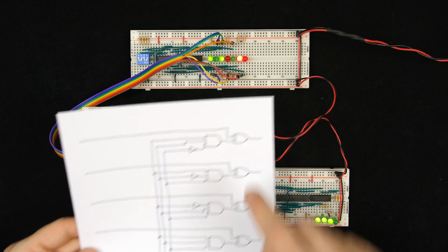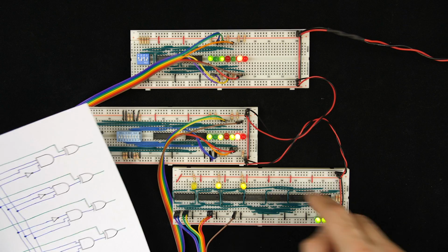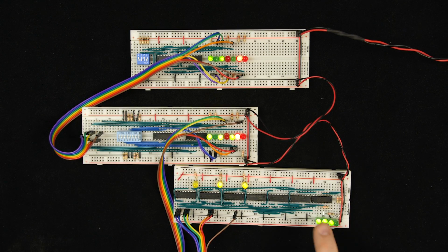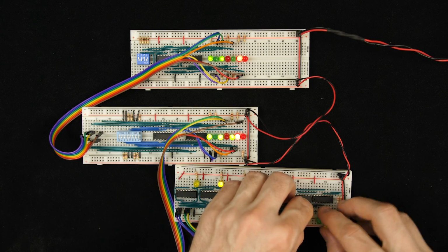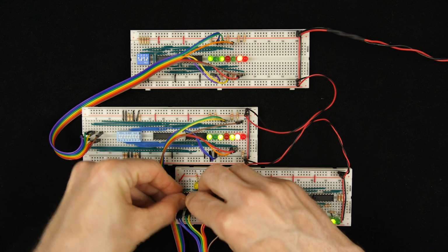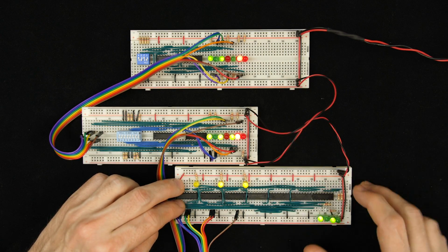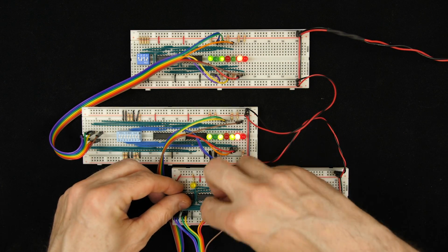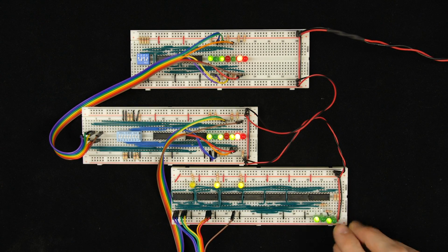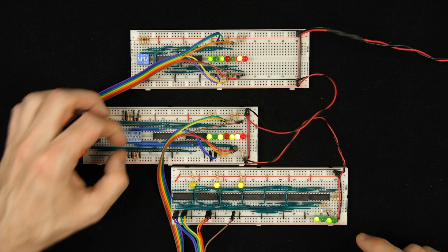We just need to hook up that second input for each of those XOR gates, which are these original data bits, and then it'll flip the one that's wrong. So here is data bit 4. That stays on. That makes sense. Data bit 3 goes off. That sort of makes sense. Data bit 2 is here. That one's on. That matches what it should be. And then finally, data bit 1. If we hook that up, that's off, which is not what it is here, but it is what it is here. So it is correcting that.